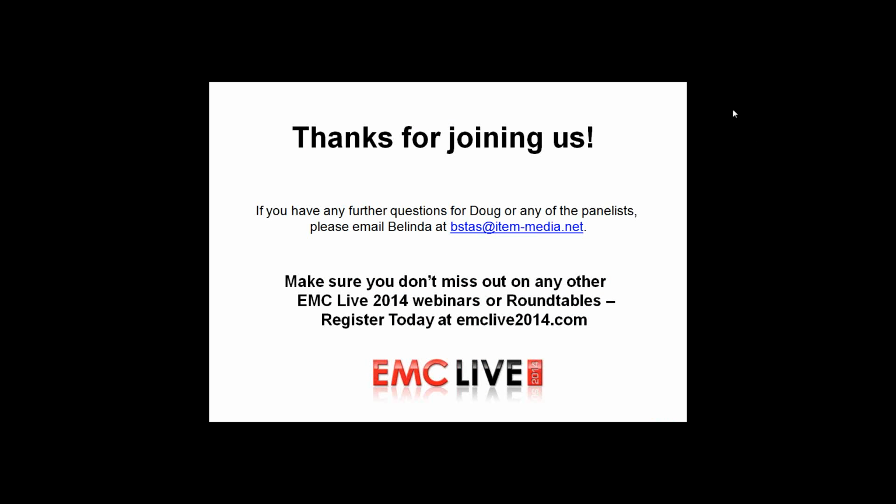Like we talked about here, as Doug has reiterated several times, the bottom line is just good EMC practice, and that's keep a clean ground plane on your circuit as best you can, with as much control over it as you have. Keep your routing such that the signal leads are short, and the component placement is compact. And if you do have decoupling devices, keep the leads short on those.